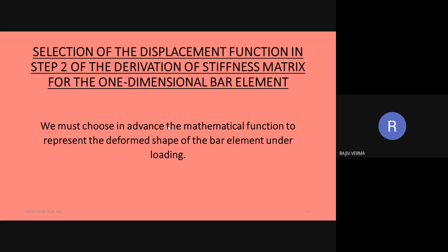It is compressed only to a particular extent, but after the forces exceed a particular limit, the member will actually buckle. Buckling is a phenomenon observed in columns, particularly columns of large length and small cross-section area, which means that the column is slender.